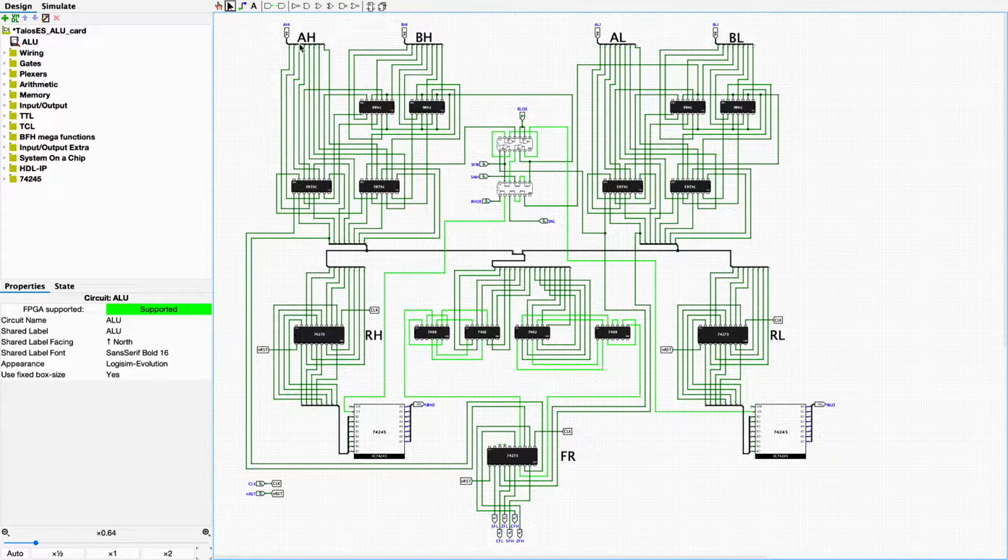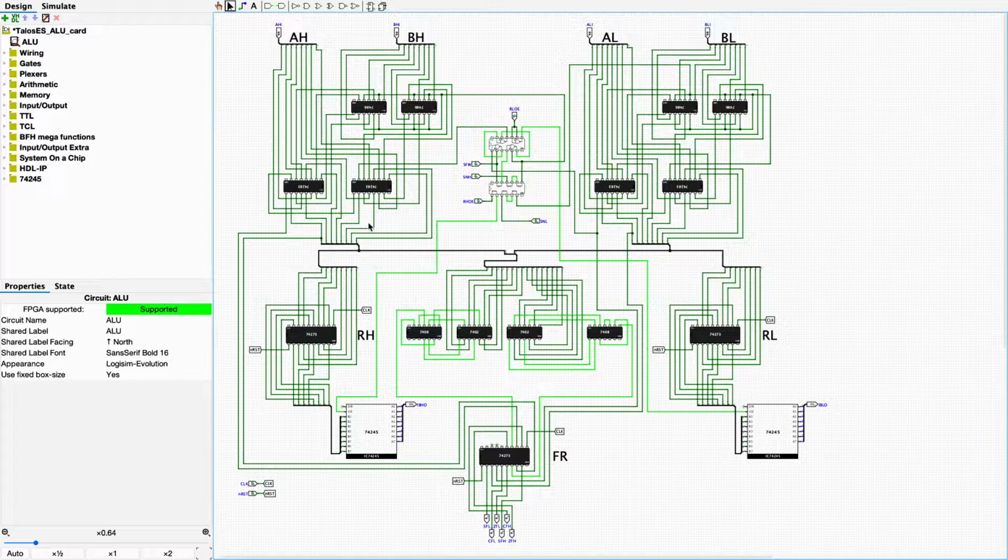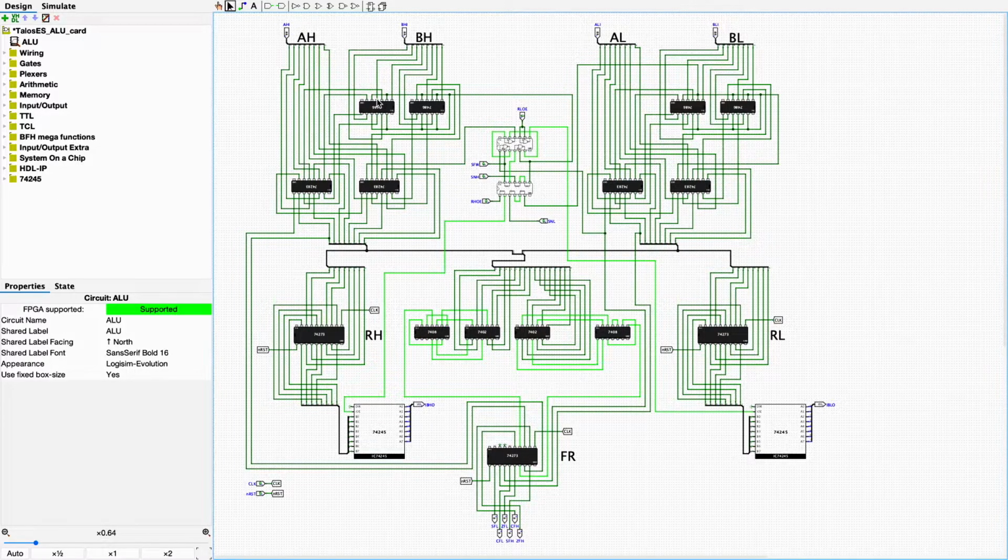The correct operand will be available in these registers, these four registers of the register file, during that cycle, but you cannot change the control bits as to address those registers in order to be written into by the result of the ALU, because you will be writing into the register that contains the operand of the computation, and you will not be able to predict what's going to happen. It will be a mess. You will compute wrong results.